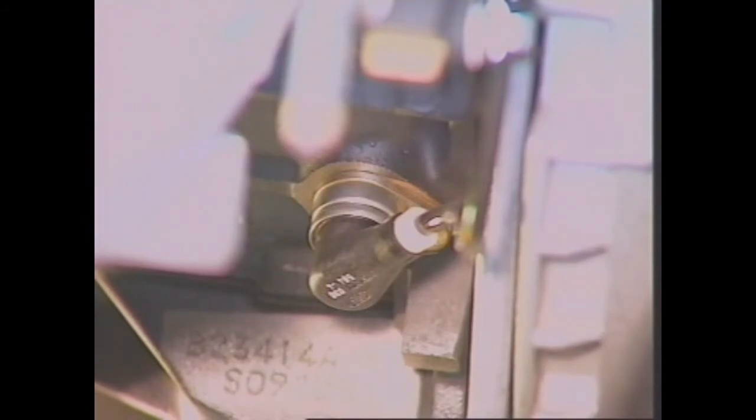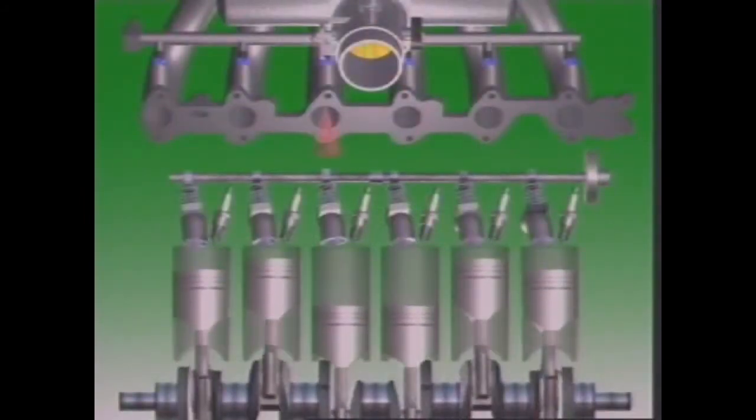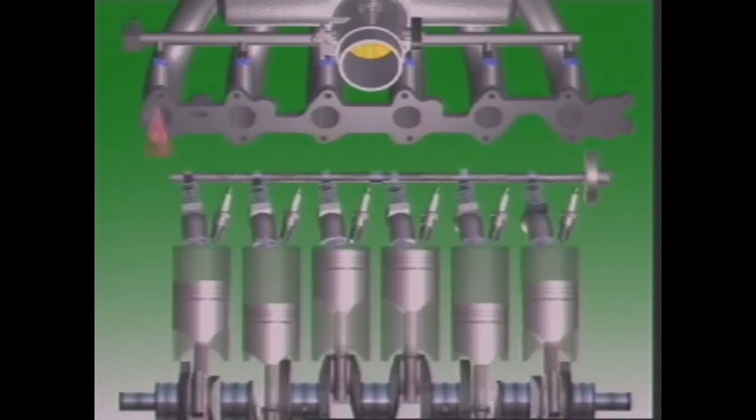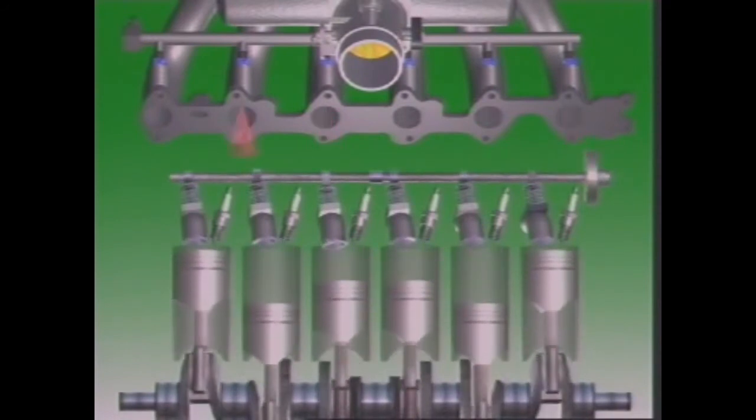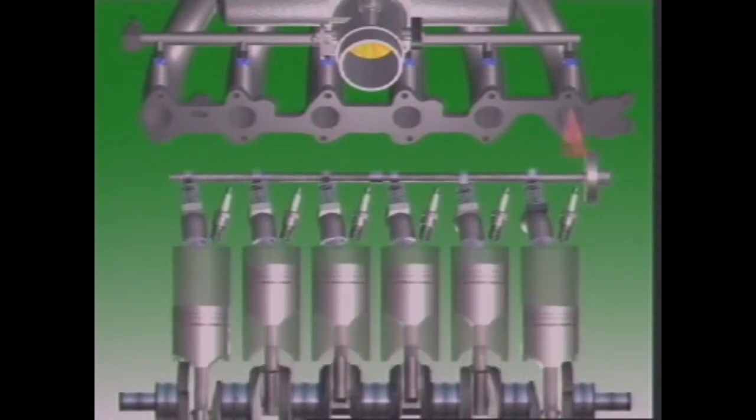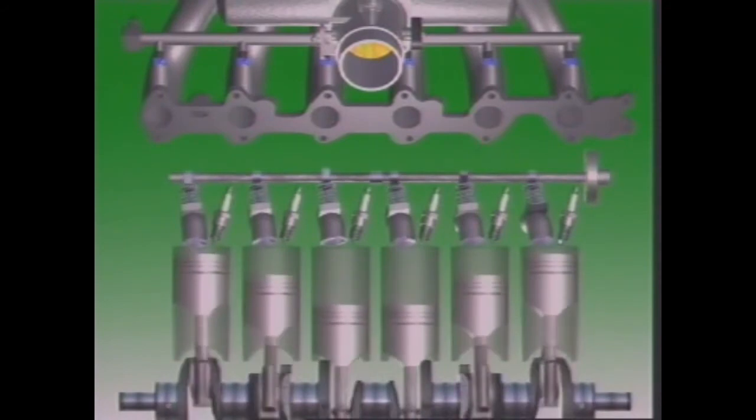When the sensors are on the crankshaft, a separate sensor is needed for camshaft position. It identifies when to commence injection for the number 1 cylinder. Injection for the other cylinders then occurs in the same sequence as the firing order.